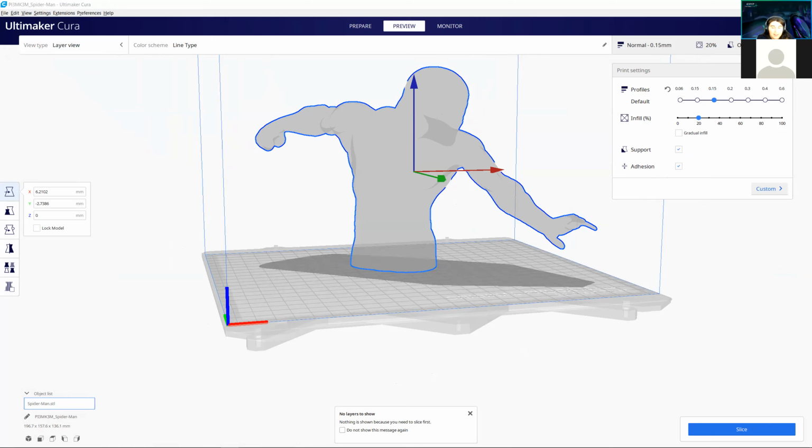Oh yeah, and to answer Addie's question, the higher the infill, the denser the model. So I'll show you, this was at 20% infill. If I run this at 80% and I reslice it, the slicing usually takes a little longer, the more time and the more work the printer will have to do. But that's usually with just the bigger models. Usually with smaller models, the slicing's really quick.